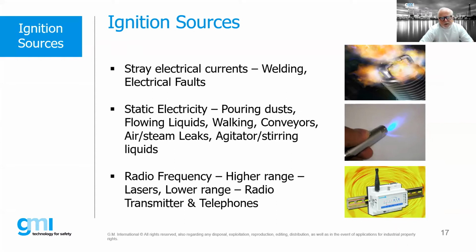This is one of the issues that you find with non-metallic equipment in hazardous locations. Manufacturers will add things like carbon black into some of their fiberglass reinforced polyester enclosures to address the buildup of static electricity. We want to limit the amount of surface area of non-metallics to a point where that static electricity can be dissipated. And that's why we ground so many of these items, to make sure that we can bleed off as much of the static electricity as possible.